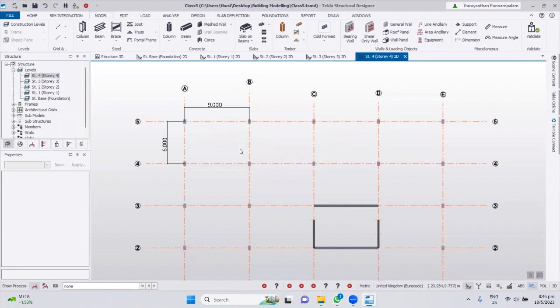In the Y direction, my drop panel size is 2 meter. Based on my rule of thumb, 250 thickness is sufficient for this area. If the slab thickness is 250, normally the drop panel thickness is around 1.75 to 2 times the slab thickness. So I go with a 450 thick drop panel. My drop panel size is 2 meter by 3 meter by 450 mm thick.